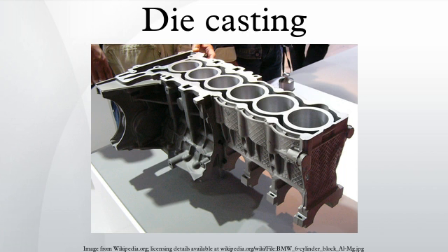The ejector pins are driven by an ejector pin plate, which accurately drives all of the pins at the same time and with the same force, so that the casting is not damaged. The ejector pin plate also retracts the pins after ejecting the casting to prepare for the next shot. There must be enough ejector pins to keep the overall force on each pin low, because the casting is still hot and can be damaged by excessive force. The pins still leave a mark, so they must be located in places where these marks will not hamper the casting's purpose. Other die components include cores and slides.